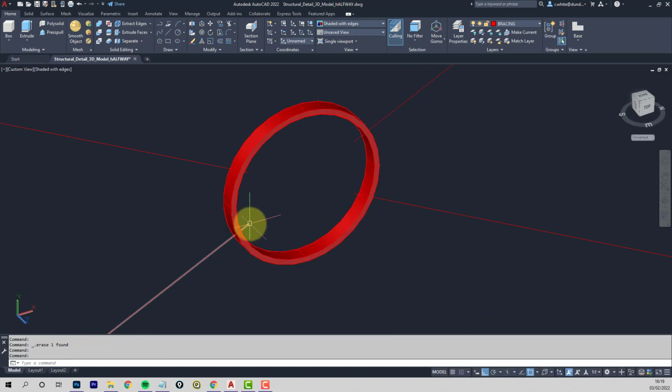But these are just hairline width. We need to solidify these, so I use a circle there. So C, enter, and just a little circle, 7.5 millimeter radius. Copy that another 3 times, because when we use the next command, it uses the shape up.